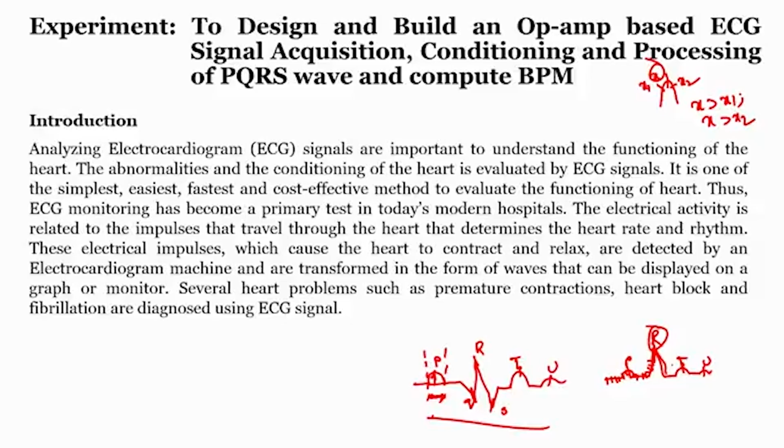If we recall what the professor said in the class, we understood that the QRS amplitude peak is comparatively very large when compared to the other peaks in the ECG signal. So, if I put some threshold, that means out of the complete ECG signal, what is the maximum peak that I am getting? In that maximum peak, I will fix some threshold somewhere around 70%, somewhere around 50% of the peak. So that it will allow only the R peaks to pass through, and the peaks below the threshold it will not allow. Then I can easily find the R peaks, and if I can calculate how many R peaks there are, my job is done, right.